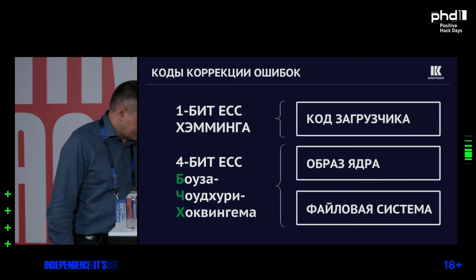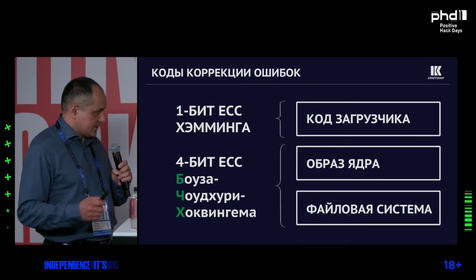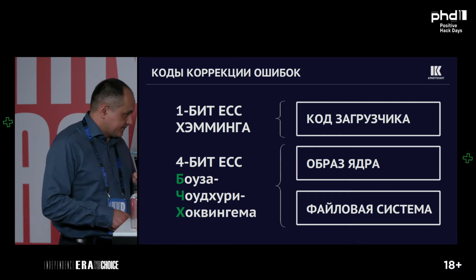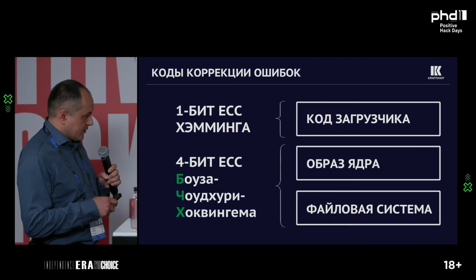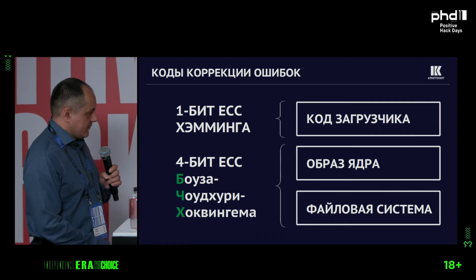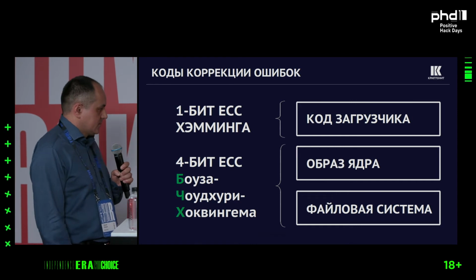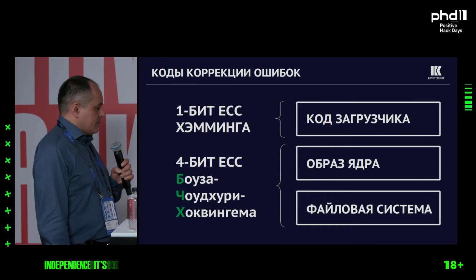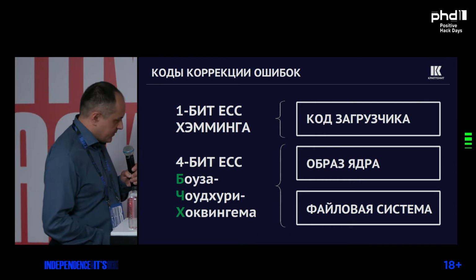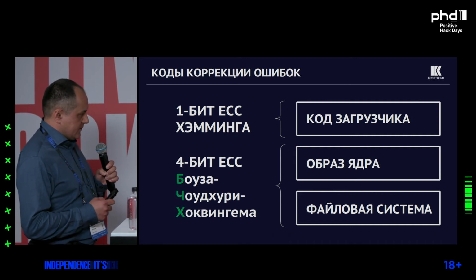And in some cases, the loader is placed in a number of places, and it can read it from different places, checking whether the checksum is okay. Thus, the error correction is delegated to FlashFX. The second type is the ability to fix 4 bits for 512 bytes.